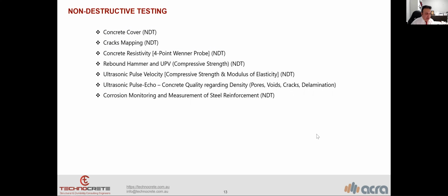And then corrosion monitoring, measurement of the steel reinforcement. For this, we have different types of electrochemical-based corrosion monitoring for site and field to get accurate results.